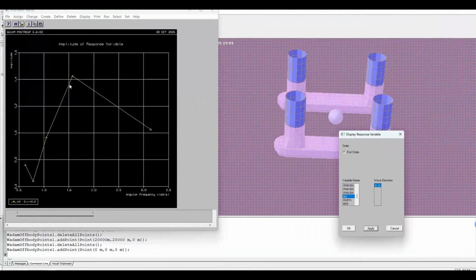Then, you add this value to your initial height at the very beginning. The initial height I set earlier was 10 when I set P1, so here, 1.37 plus 10 equals 11.37. So, when the wave frequency is 1.5, its crest height is 11.37. That's how you calculate the crest height.